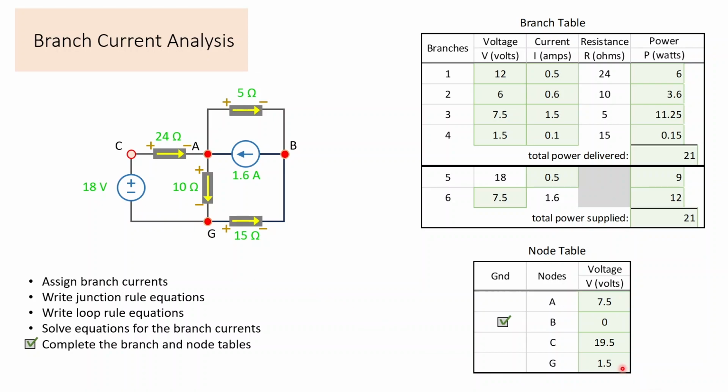That's 1.5 volts. Any of the 4 nodes could be ground, and the others can be computed by following any pathway through the branches, since volts is path independent, any pathway to go from one node to another starting from ground. We now have a complete solution.